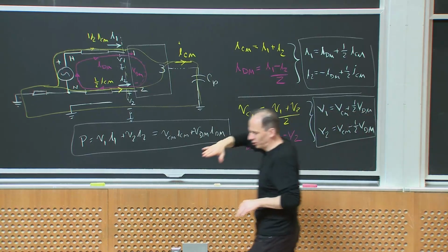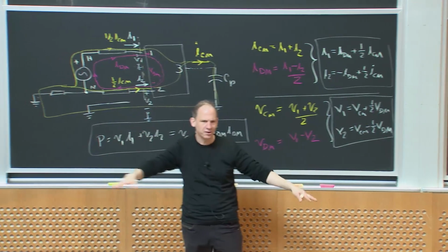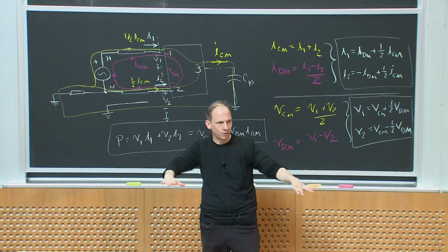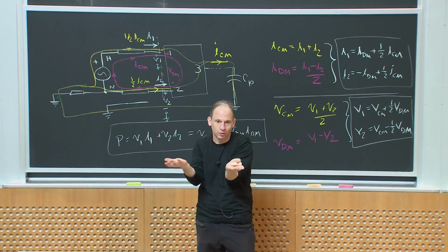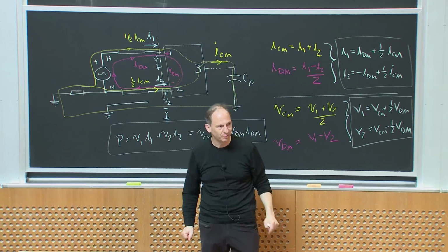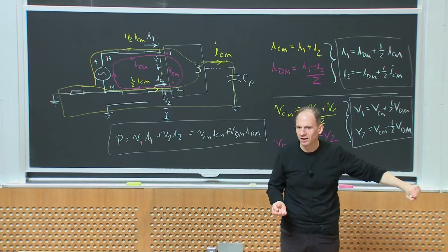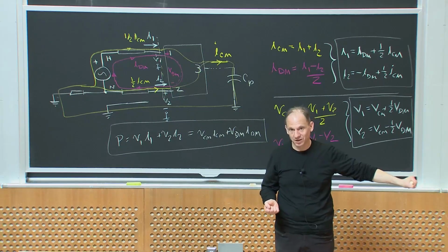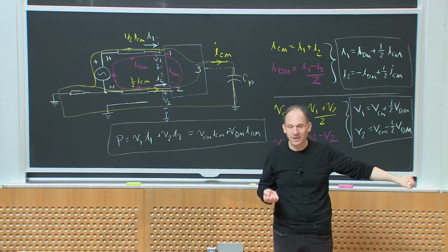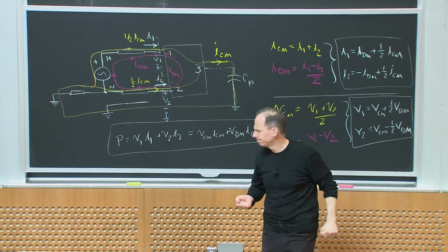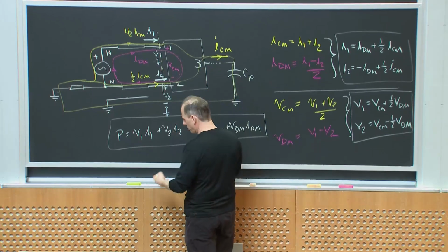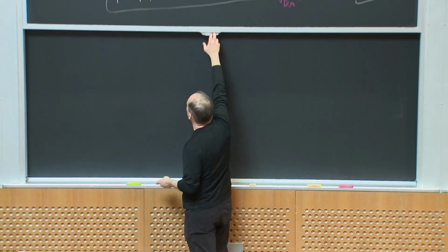Now, in some cases, you can get away with a single-ended filter, right? If this whole thing were built on top of a ground plane and there were no wires going anywhere, and there's just one big ground plane, well then sure, you only need to filter one lead because everything else is traveling in the big ground plane. But if you have a device that's connected over some cabling, you better think twice because there could be some unintended path back, okay? All right, so let's go think about how I would design a filter to deal with this.